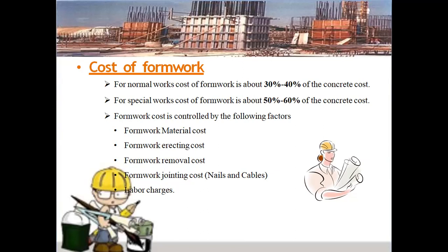So this formwork cost is not only seen during the construction process, while preparing this formwork. The cost of the formwork includes the material cost, the design cost, and after curing and casting of the concrete, the removal cost, and also the jointing cost, the nails and cables required for joining these formworks, and the labor charges of those who fitted the formwork.